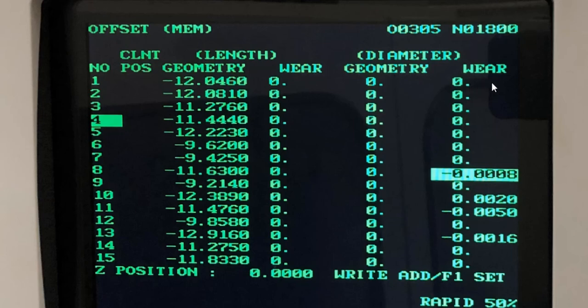Okay, if I wanted to leave it big, sometimes your tolerance on your print will say 4 inches plus 10 minus nothing, then I purposely want to add 5 thousandths or even closer to 10 just to be on the high side, and then the machine will think that the tool is big and actually stay away from the geometry, leaving the part larger. So I hope that makes sense.